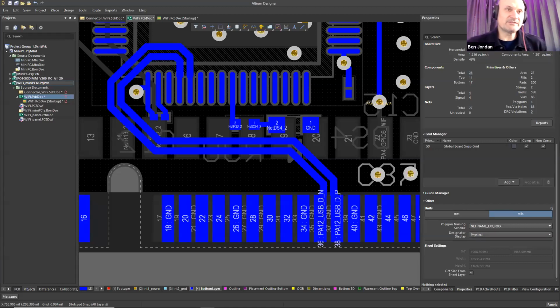Here's the thing about trace dimensions and impedance: it's all relative. If you're using a field solver, they're unitless. Everything is normalized basically down to pixels in an image, and that's how ATLC works. So you don't even have to say this trace is 11.596 mils wide.